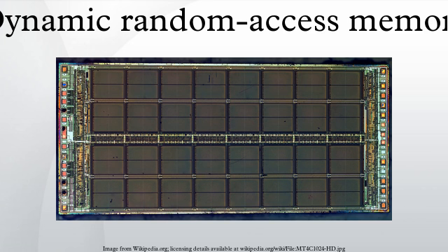Memory size of a DRAM module. The exact number of bytes in a DRAM module is always an integral power of 2. A 512 MB DRAM DIMM actually contains 512 MB = 512 × 2^20 bytes = 2^29 bytes = 536,870,912 bytes exactly, and might be made of 8 or 9 SDRAM chips, each containing exactly 512 Mb of storage, and each one contributing 8 bits to the DIMM's 64 or 72 bit width.